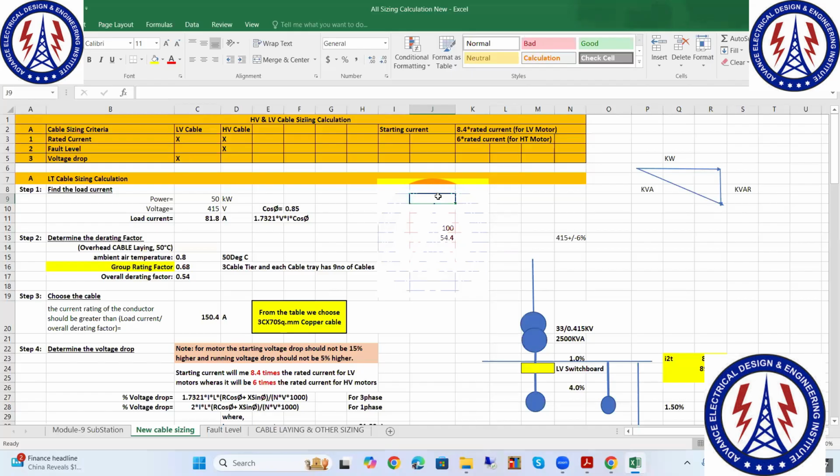Okay, actually, I asked it very specifically why, because I have seen on the EHV cables, especially on 600 square mm cables, where I could see that earthing has been done on both ends, because it runs for kilometers, 2-3 kilometers. So we could see that it is earthed at both ends. I don't think that is correct. I don't think so.